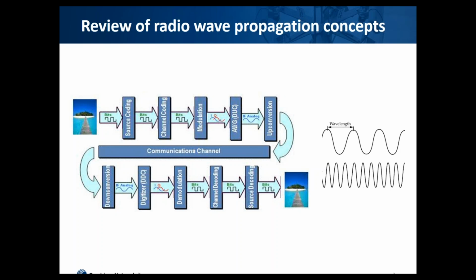At this point, the signal travels through the channel. So this is what the input to the channel is. It is the waveform generated by the transmitter carrying the bits that represent the data to be transmitted. When the waveform travels through the wireless channel, many things can happen. We'll see some examples of why the signals might degrade in the next slides. But even in perfect conditions, the signal arriving at the receiver at the minimum is attenuated, meaning that its amplitude is lower. The longer the signal travels over the air, the lower its amplitude at the receiver becomes, and the harder it is to distinguish which signal was transmitted.